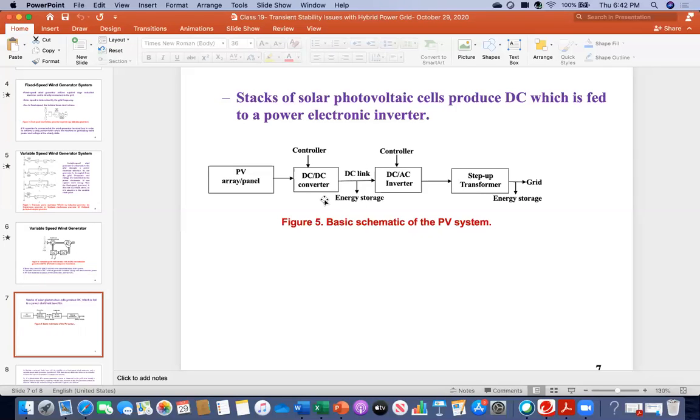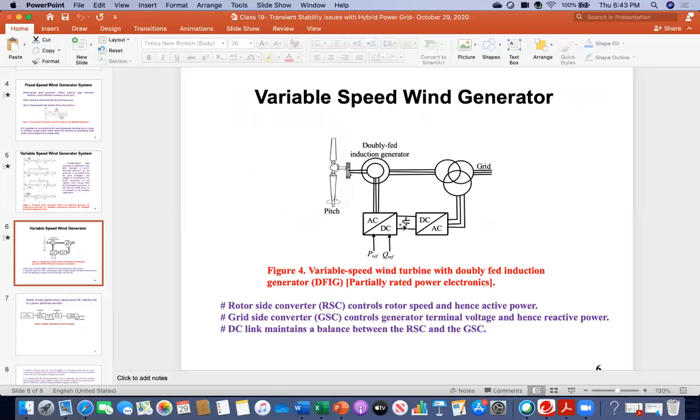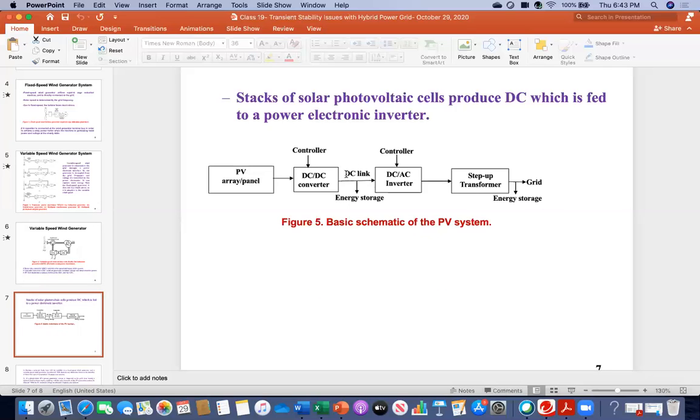So anyway, here we are producing some voltage, for example, 150 volt or 200 volt, and you increase it to a certain level, assume 400 volt. But then here again, you need a capacitor. I am not showing it, I just wrote DC link. That will look like this type of capacitor. DC link means it has a capacitor that will hold that constant voltage.